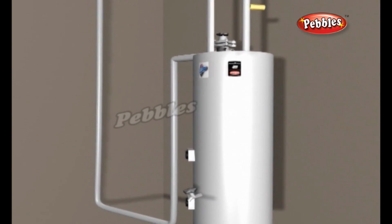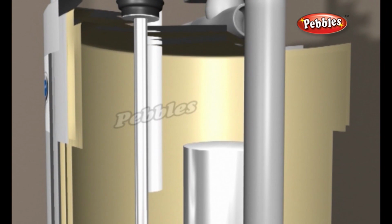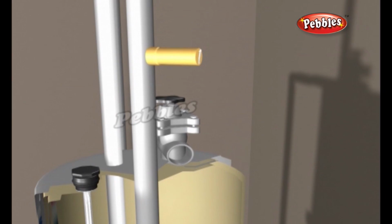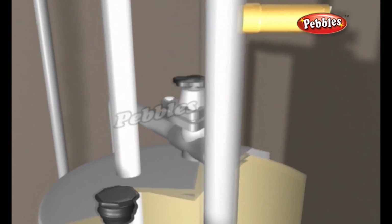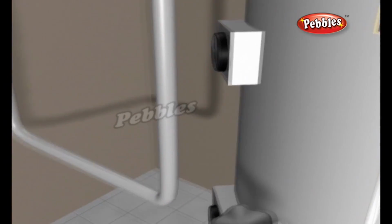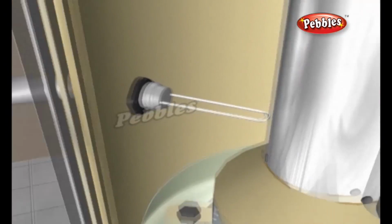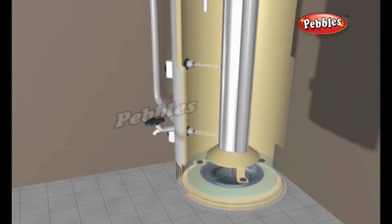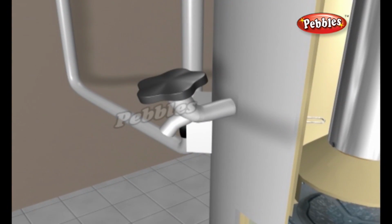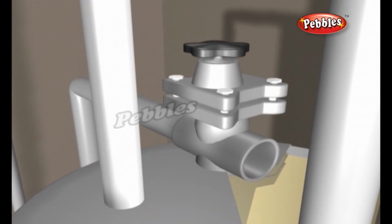A water heater consists of the following parts: a heavy inner steel tank that holds the hot water, insulation surrounding the tank, a dip tube to let cold water into the tank, a pipe to let hot water out of the tank, a thermostat to control the temperature of the water inside the tank, heating elements to heat the water, a drain valve that allows you to drain the tank to replace the elements or move the tank, a pressure relief valve, and a sacrificial anode rod to help keep the steel tank from corroding.